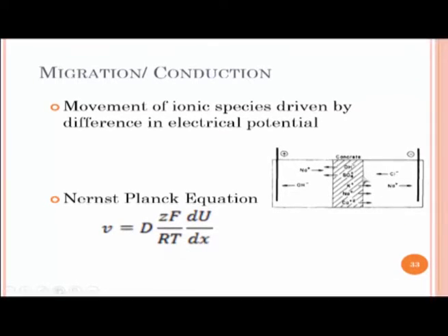When they are trying to pass through the concrete, obviously they will change the properties of your concrete. So here the property we are measuring is the charge that is passing through the concrete. When the potential difference is applied, there is a current that is passing through concrete. The chloride which is getting driven to the positive electrode has to go through the concrete.